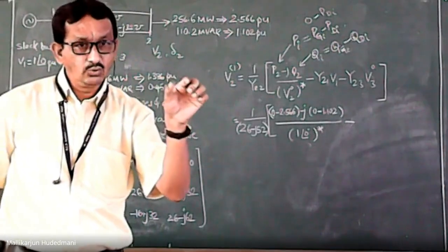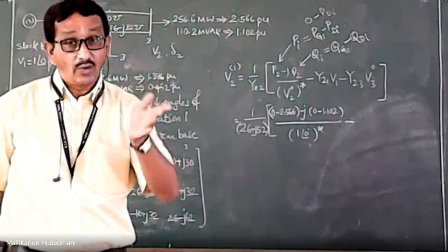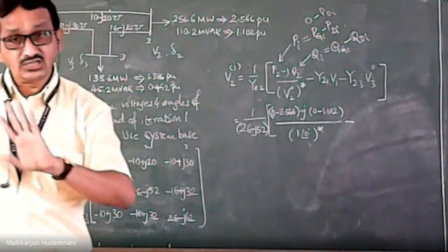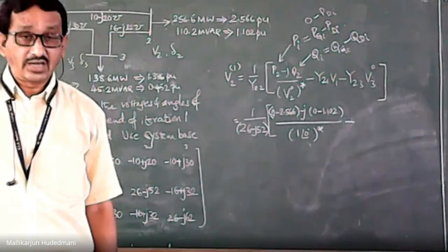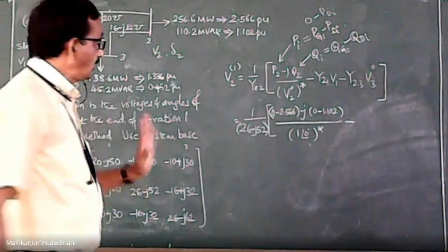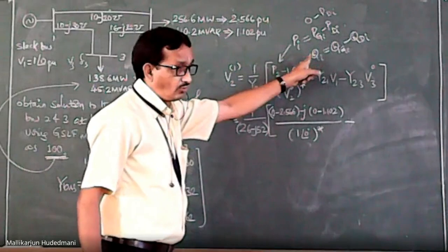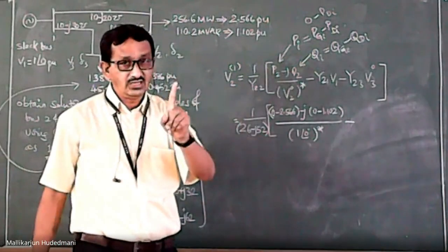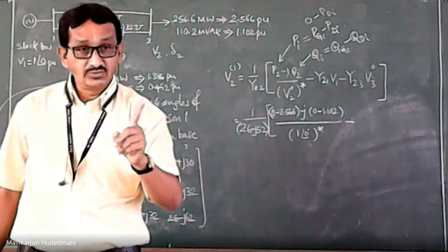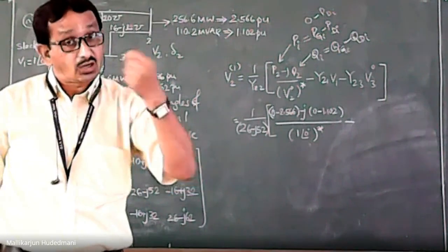QG minus QD is my requirement in the position of Q2. That's enough. We will not worry about plus or minus because it automatically changes sign if it is a load or a generator. You will understand this concept, which I have focused on the board, and it is very necessary. You have to look at it with this angle only. Is the data in the problem given directly as Pi, Qi, or do I need to work out Pi, Qi?